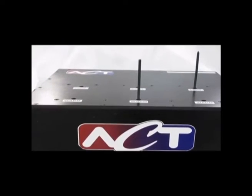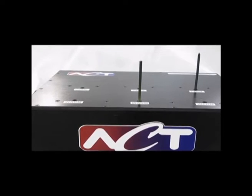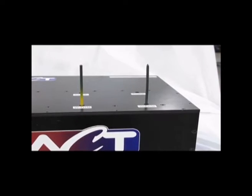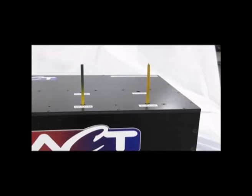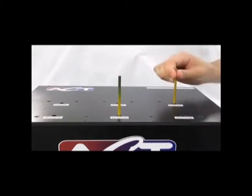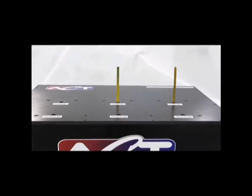The hot side is well above the 40 degrees C color change temperature. Copper has a thermal conductivity of 400 watts per meter K, which is high for most metals. You can begin to see color changing as the copper conducts heat away from the heaters below. Now we'll place the heat pipe into the hot side. Notice that the heat pipe reaches steady state almost instantaneously with minimum temperature gradient compared to the copper rod. Now we'll move both the copper rod and heat pipe into the cooler side. The heat pipe simply changes the direction of the thermodynamic loop and reaches the lower temperature steady state in seconds, while the copper rod struggles to reach that steady state temperature.